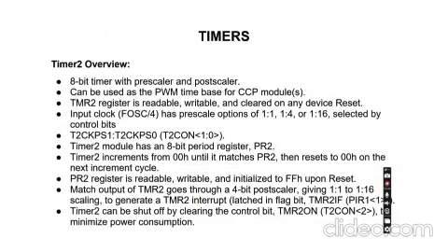The next topic that we are going to explore is timers. Timers are a default peripheral in a microcontroller, used to calculate time. Timers are also available in different sizes like 8-bit, 16-bit, 32-bit and 64-bit. In the timer, there are two scaling concepts, prescaler and postscaler. Prescaler is used to scale the time taken by the tick. Postscaler scales after how many overflow interrupts will occur. These are the two main scaling concepts in timers.